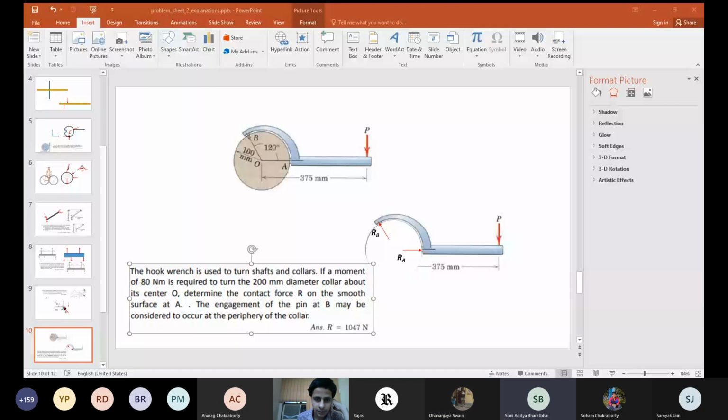We have not considered the circular body in the FBD, which is held between the two. The circular body is in a state of equilibrium if the moment is 79.99999. It will start moving if it becomes 80.00001. But I am having a doubt: if we consider the FBD of the circular body, then who is providing moment to that body? How will it rotate?